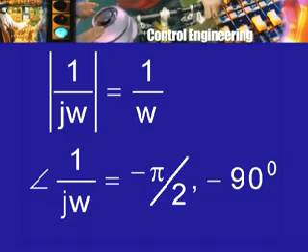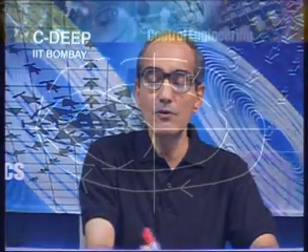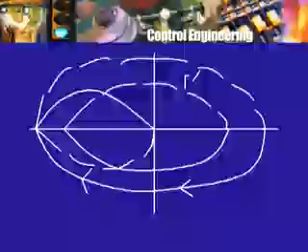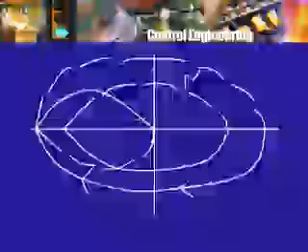and therefore, the polar plot or the Nyquist plot or the frequency response data will give you a plot which is going to look like what? At very low frequencies, there is no phase shift difference. So, it will start here as it did, and then it will go around because of the lagging phase shift. However, as the frequency increases to a large value, the phase shift is not going to be minus 180 degrees, but it is going to be minus 270 degrees or plus 90 degrees, whichever way you want to look at it. And therefore, if I actually did an experiment, the polar plot that I will obtain will look more or less like this.